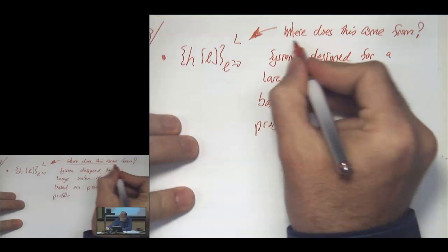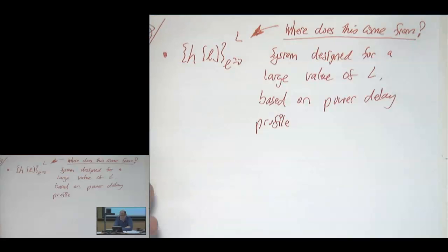But I do want you to think about this. This L is just not something we can take for granted. Now, if we were talking about a pure signal processing class, we would use a technique called order estimation. Similar to system identification, when you're identifying an unknown, let's say FIR system, there's a set of mathematical tools that help you estimate the order of that system.